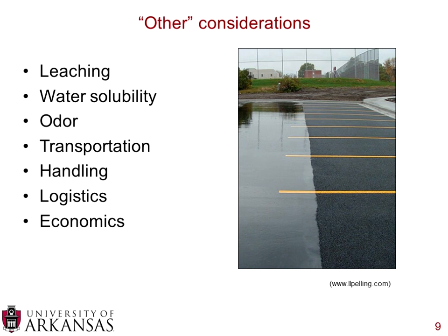You also want to make sure that the biobinders are not water soluble. As it rains, you don't want them to begin to dilute and disperse and lose their good performance characteristics, as we defined on the previous slides. You want to minimize odor. No one appreciates bad odors, and sometimes when you're putting these materials into pavements, you're not sure exactly how the smells will affect the general public.